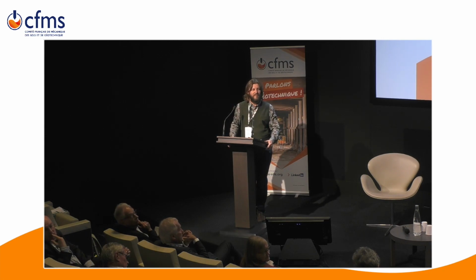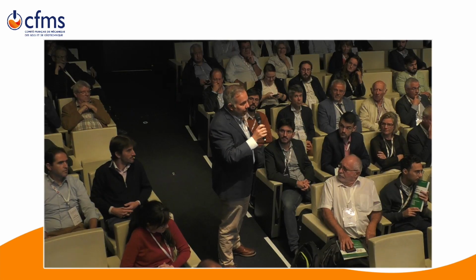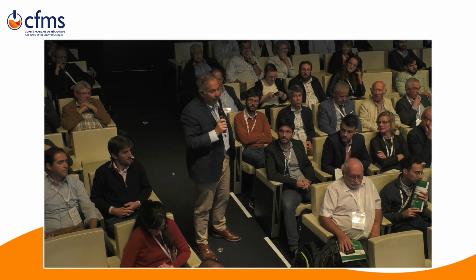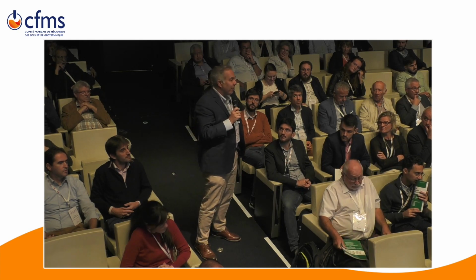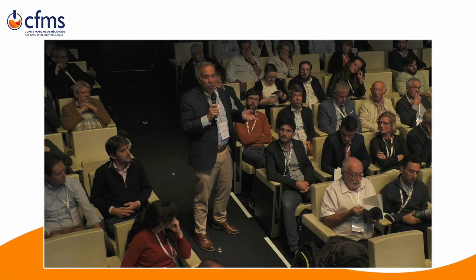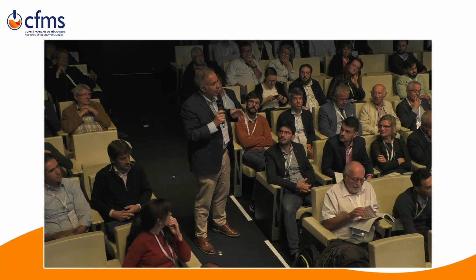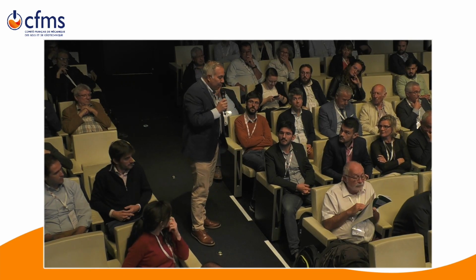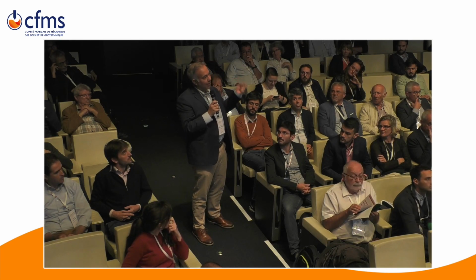Yannis Anastasopoulos from ETH Zurich. Thank you very much for a very nice presentation, and especially the centrifuge test. I enjoyed it a lot. I liked very much that you mentioned the scale effects that you may have because of grain size. We did some pile tests, and there we had the same problem. What happens is that the mobilization is a function of the grain size, which we are not scaling down, which means that in the centrifuge you will have the same mobilization displacement as in reality.